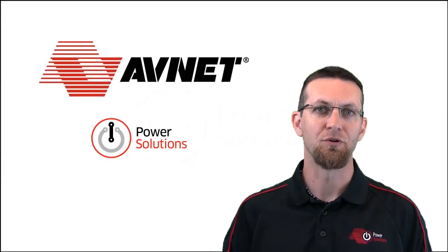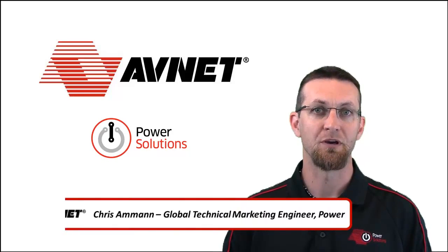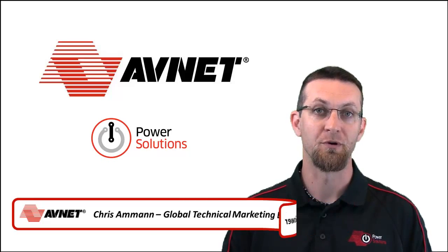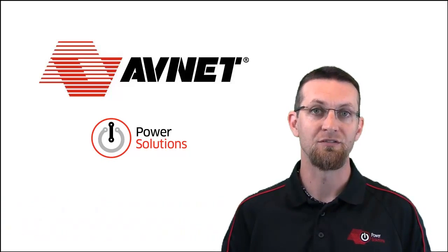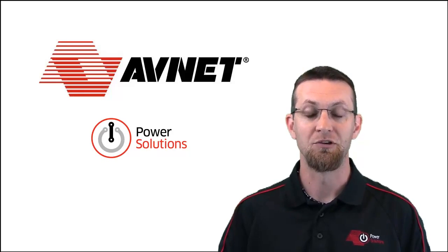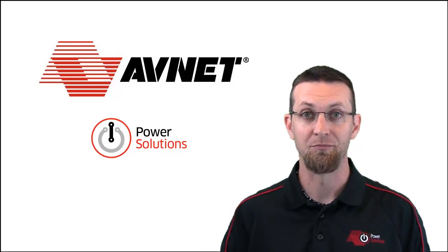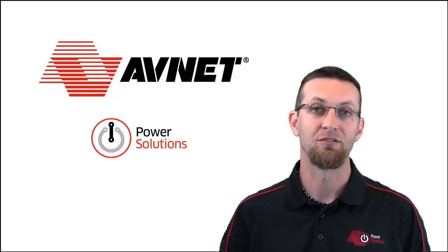Designing the power supplies for your transceivers can be the most difficult aspect of your power design. These supplies typically require extremely tight tolerances as well as very low noise specifications. The reason for this is the analog nature of the interfaces that you're powering. Any type of noise, any type of regulation error that's introduced on the power supply is going to be translated onto your outputs. This can result in limiting your maximum data rate, bit errors, and things like that.